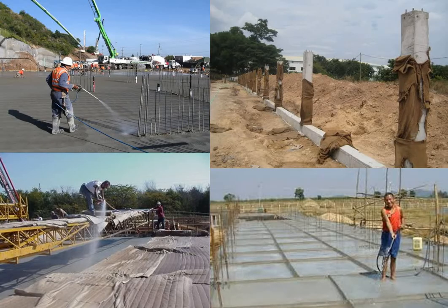Okay, here you have different types of curing. You can see water curing, and this one is membrane curing. You have special chemical membranes which have the capacity to retain the water. Then you have gunny bags. You might have seen wet gunny bags laid over the concrete. Then ponding.